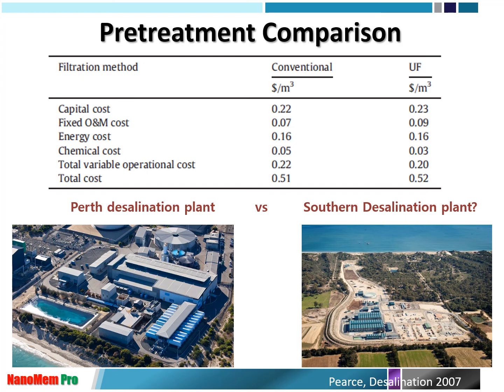So their water quality is almost similar, and then they compared the overall pretreatment performance, and they believe the ultrafiltration gives very consistent operation for RO, because UF is a very straightforward molecular size of the pore, and then all the contaminants can be removed.